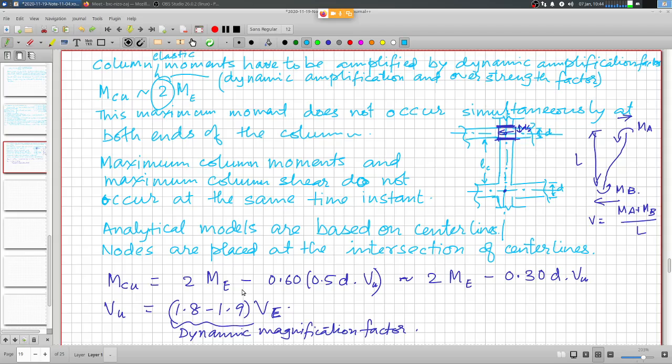Usually we don't even reach the maximum limit of longitudinal reinforcement because of the requirement to have stout columns. It's impossible to have a very slender or very thin column section in a seismically active region because of drift considerations. There is a limit on the acceptable drift, and from that consideration the column dimensions are going to be very large to achieve sufficient stiffness.